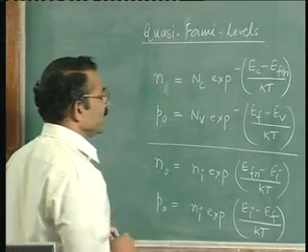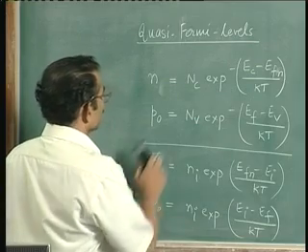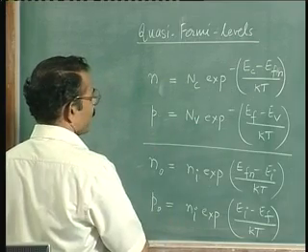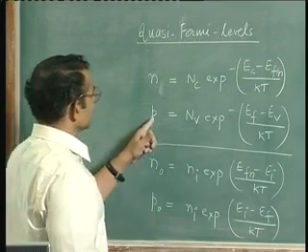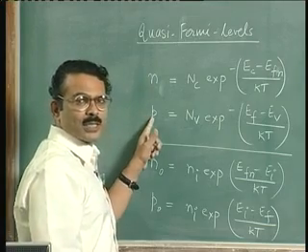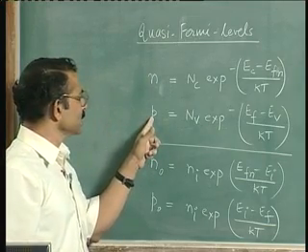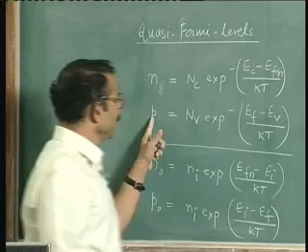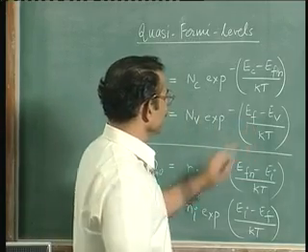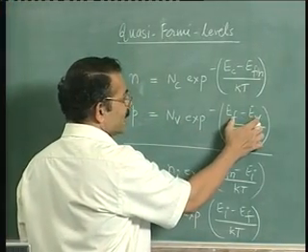Now one important point is to be noted. When you want to express the hole concentration, you will note that since the left hand side has increased, the hole concentration is more because of the presence of excess carriers, because it is P naught plus delta. The right hand side should also increase, which means that this difference should decrease.